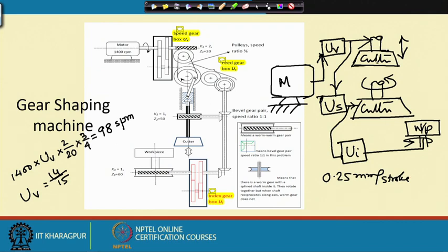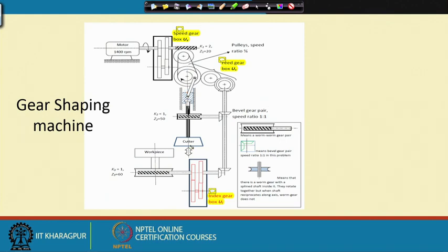So, let us start from one stroke of the cutter. When it executes one stroke, the big pulley rotates once. So, the feed gearbox is getting an input of 1 rotation, not RPM. So, US 1:1, then it enters K by Z equal to 1 by 50. This gives the number of rotations of the cutter. Per rotation, the cutter executes a circumferential motion of one circumference, pi d.